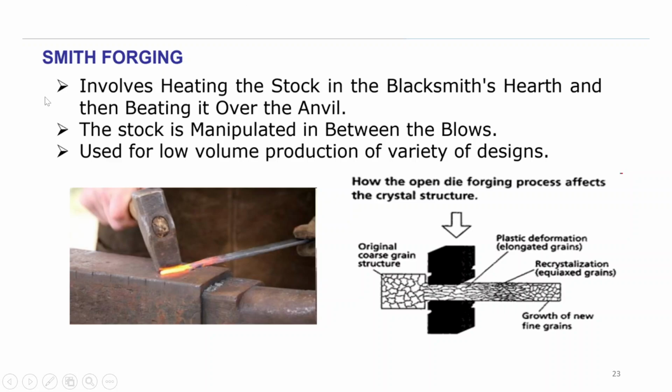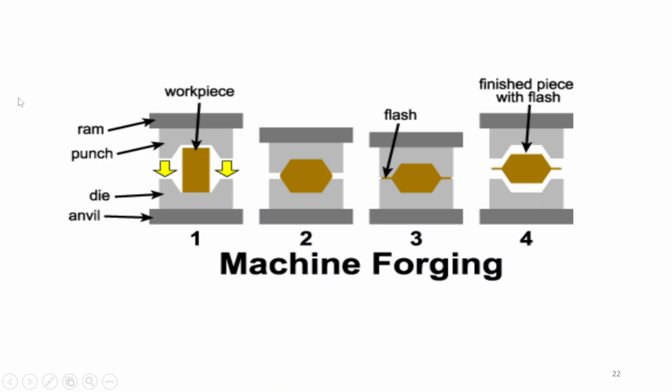Next, how is the forging process different from the extrusion process? Extrusion is different, as in extrusion you are providing a particular temperature and squeezing your material through a particular opening. Here, using hammering or the ram speed between the dies, you are providing the shape of the die to the material.